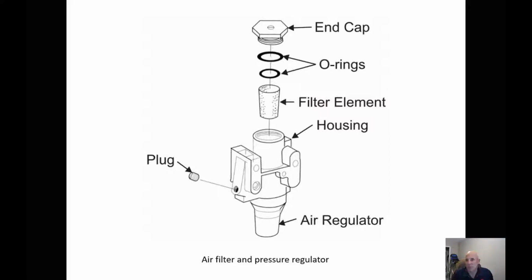Some air systems aren't like that, so again, it depends on the manufacturer how the air system is set up on the vehicle. It takes system air of, let's just say, 120 psi and brings it down to roughly 60 to 63 psi. And that's the pressure that's used throughout the air system for shifting.